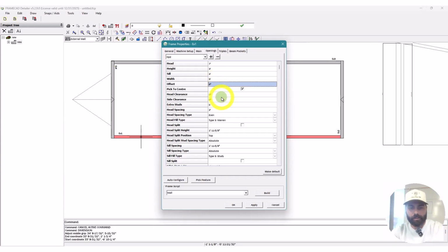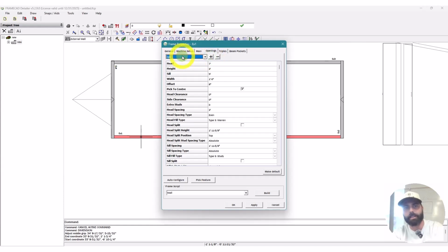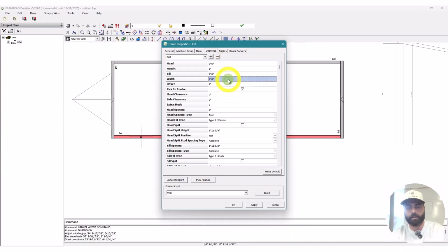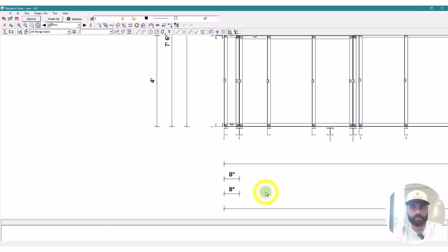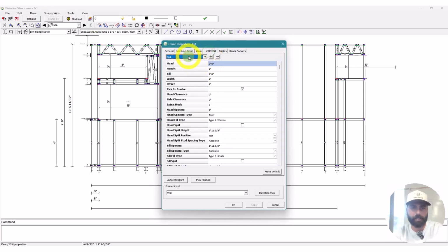We'll go ahead and add one more clerestory and call this at a 9'6" header. That's a 2-foot window. 5 feet wide, minus 4, so this will be at 21 foot. And then we can go ahead and see how this looks. Not great. All right, let's say opening 2, offset, this was supposed to be 72 inches.